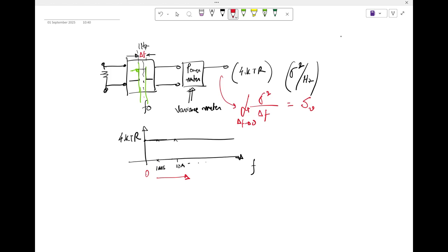So let's say you take a sinusoidal signal and you express it in terms of Fourier series coefficients: one will be a positive frequency, the other will be a negative frequency, right? e to the power j omega t plus e to the power minus j omega t. So one is at omega naught, another is at minus omega naught. And the power, or the amplitude, gets distributed in this case half here, half on that side, right?